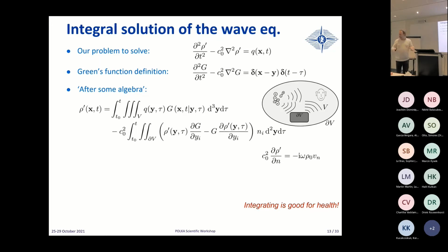Now, if you are looking at reflection by this table, I can presume a priori that my voice is not loud enough to make the table vibrate very strongly. So then you have the other problem, which is a problem of reflection. The reflection is simply the fact that you have a certain acoustic velocity, and when it reaches the table, it must go to zero. So there's a non-penetration boundary condition, and a kind of minute reaction force is exerted by the table to bounce the wave back. This corresponds to this term. This is effectively the acoustic reflection.